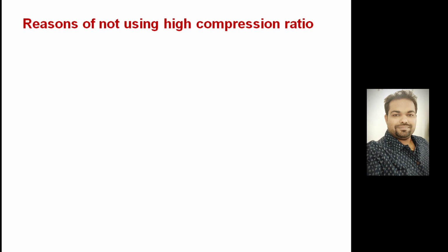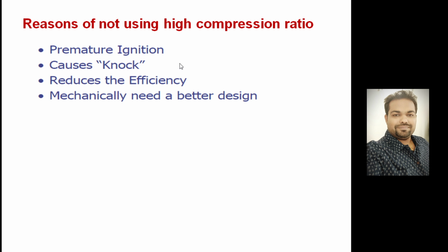Pre-ignition occurs in a cylinder and will cause a noisy operation, because it is like an explosion into the cold compressed air. Because of that, a lot of vibration issues will come into the piston cylinder device, and because of that, the engine may fail. So these are the causes: premature ignition. Because of premature ignition, as I said, it will create a lot of noise. That is called knock. It reduces the efficiency and mechanically needs a better design.